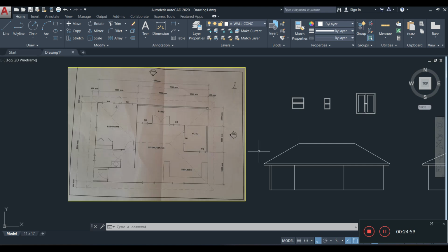So let's add our door, which is going to be somewhere between here. What I'm going to do, I think I'm going to find the center between these 2 points, and I'm going to place my door there. So let me just draw a line so I'll have something to reference with here and here. Alright, that's where the door is going to be, smack in the center there. Let me just place this on my door layer.